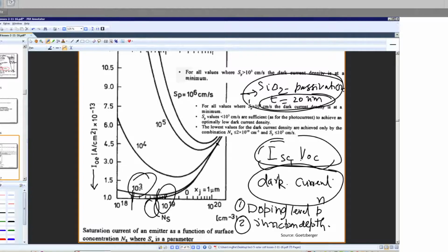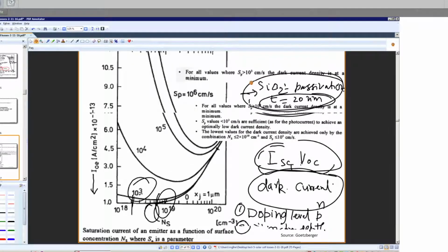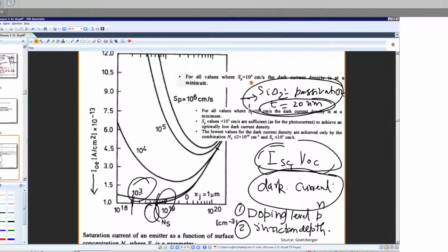If I put SiO2 which is porous or something, then you're not going to get a good passivation. So getting a good quality SiO2 is important. And this is where people sometimes learn from experience, finding out the conditions which work. It's not that easy to calculate.